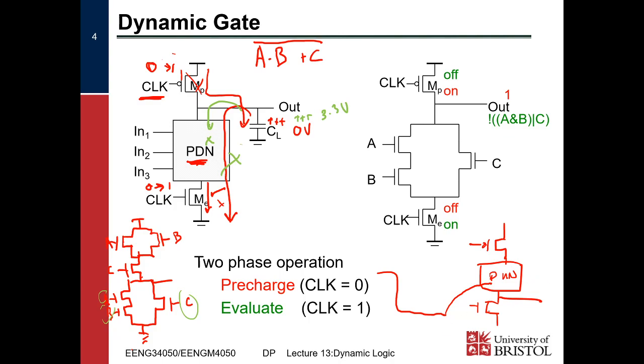So just as much as in our pull-down network, these transistors are leaky, or they might glitch, and that will cause our output to discharge. With a pull-up network case, the transistors can still be glitchy and they can still be leaky. Well, they must be leaky because they're transistors, and so they'll actually leak voltage from VDD to our output capacitor, right?